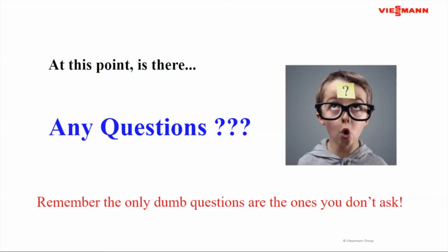What people tend to not see in the manual is coding address number 1, and we do have a class on that as well. It's that first code that you come to in our coding. There's only 14 codes in this whole boiler. It's what they call your purge mode.